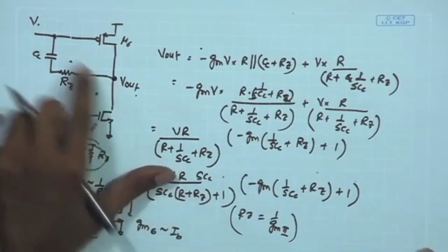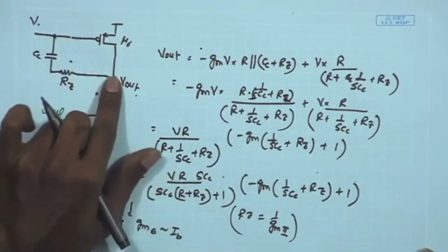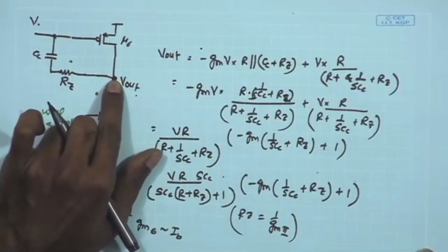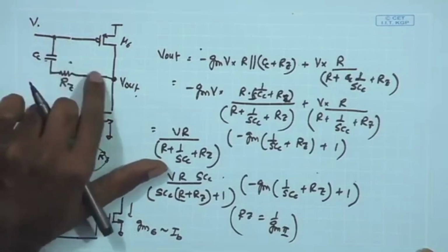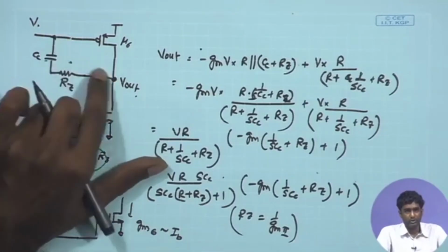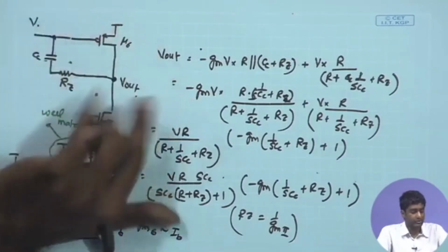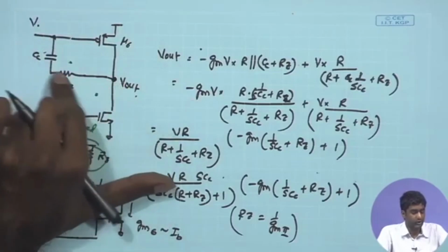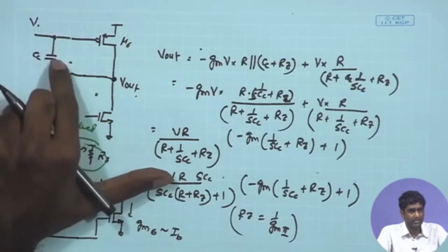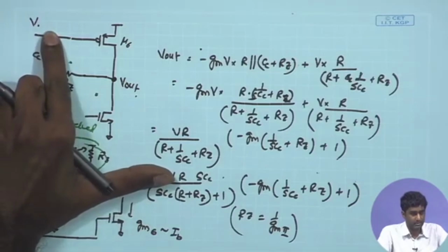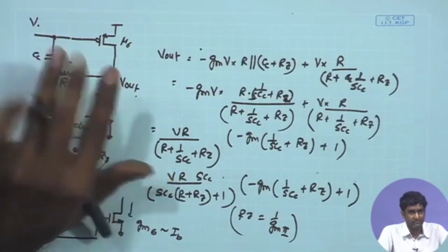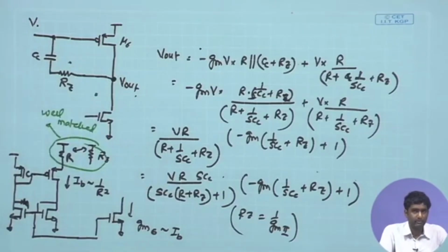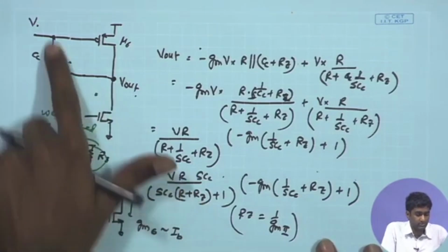So, here also if we see, ultimately this is a shunt configuration. Output is sensed using a shunt connection, V out is being sensed, so shunt, and at the input side you are again mixing current. Although the entire scheme is a voltage to voltage converter, whenever the feedback signal is mixed at the same terminal as the input quantity, we have a shunt at the input also. So, again we have a scheme which is similar to what we had in the op amp, and we use that large RF to bias the input node. So something similar over here.